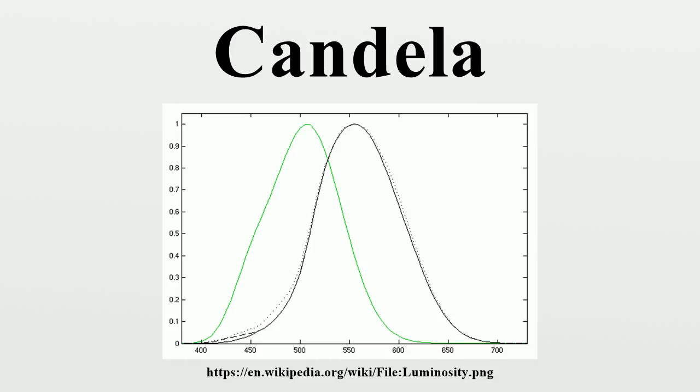What gets directly measured by a light meter is incident light on a sensor of finite area, i.e., illuminance in lumen per square meter. However, if designing illumination from many point light sources, like light bulbs, of known approximate omnidirectionally uniform intensities, the contributions to illuminance from incoherent light being additive, it is mathematically estimated as follows.